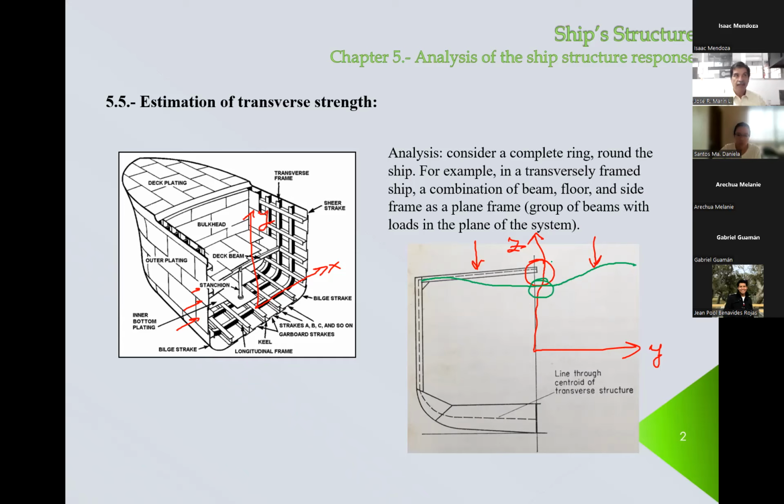Also, the shear force will be 0. There you have it. So you have only half of the structure, apply conditions here and downwards also, and then you don't need to include both sides. If you have non-symmetric loading, then you have to analyze the whole thing.